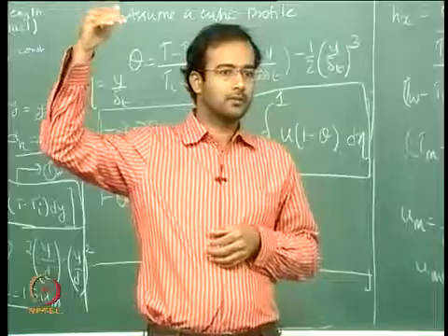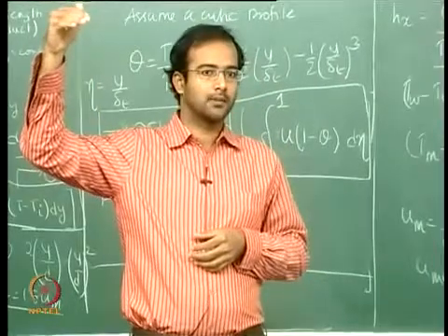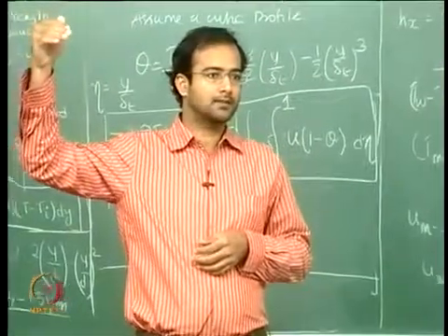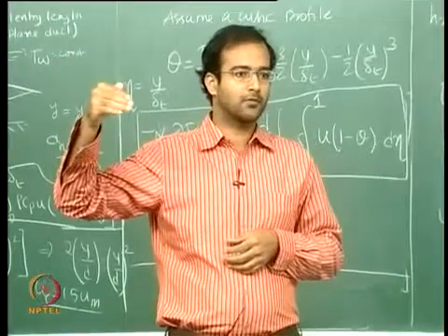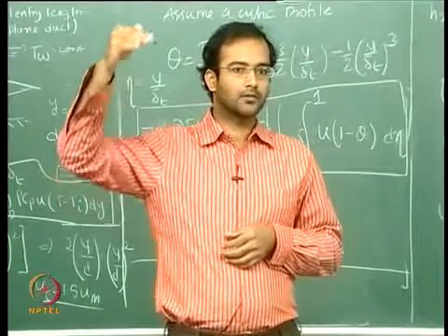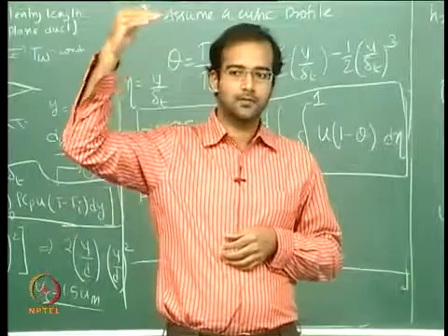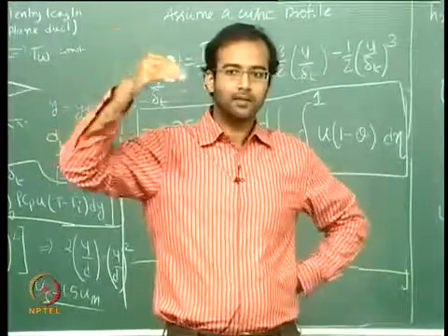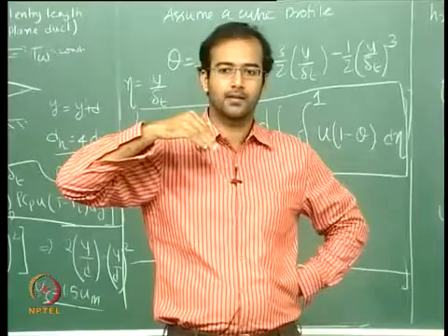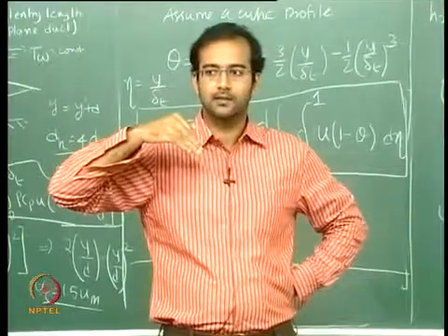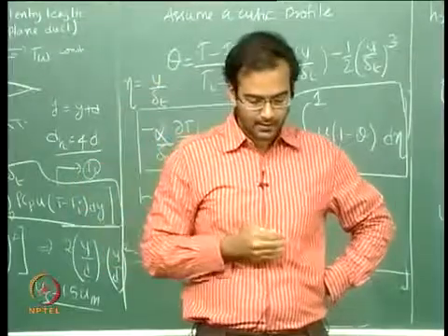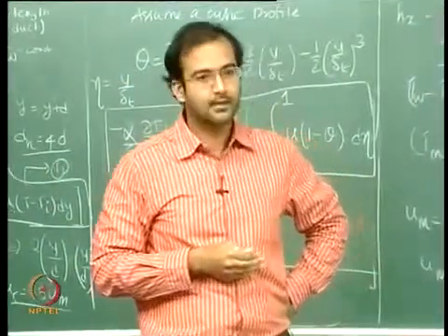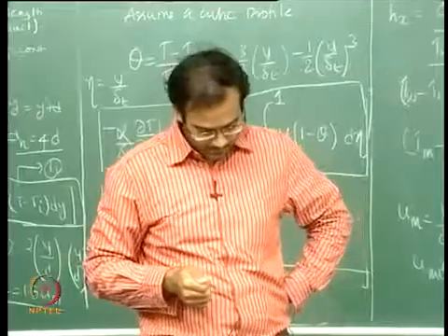Channel flow, the highest value comes for the plug flow case with the constant wall flux, then constant wall temperature, then your parabolic velocity flow. So it goes in that order, starts from 2D duct flow, then your 3D circular ducts, and then finally your triangular cross section. So this is the hierarchy in which your decreasing Nusselt number follows that pattern.